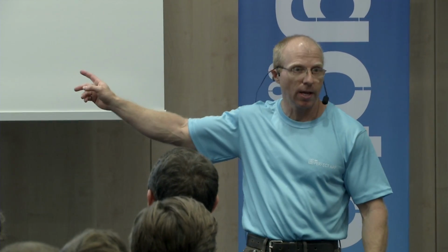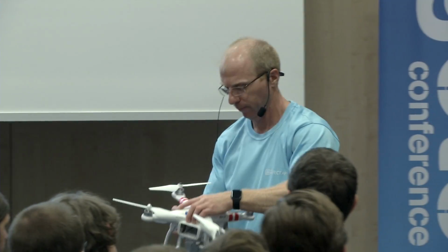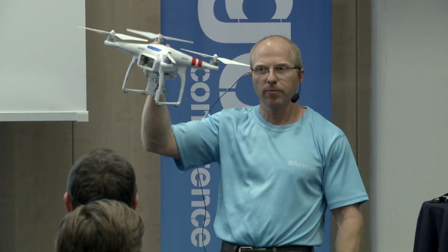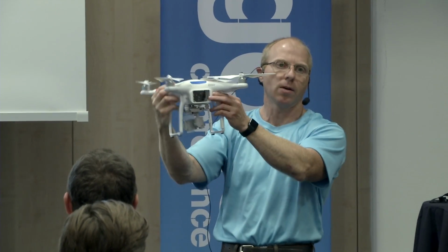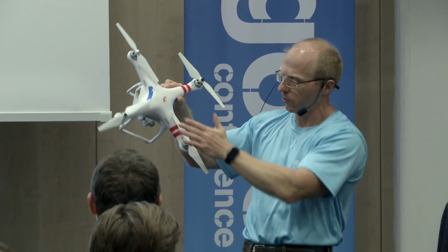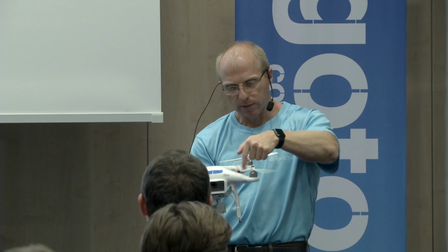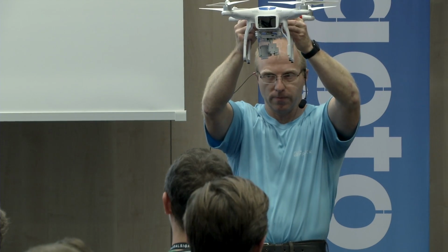How does a drone work? How do we do these things with a drone? Okay, it's pretty obvious that if we turn all the propellers in the same direction, we will have the thing turning around. So, of course, 2 propellers turning clockwise and the other 2 turning counterclockwise. Then they kind of equal out each other. And the same velocity of all propellers means we have a collective pitch, and it can rise.